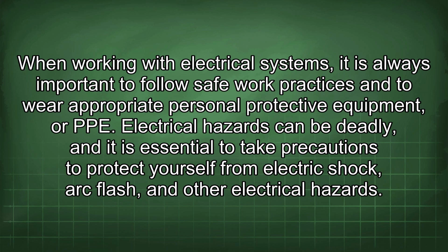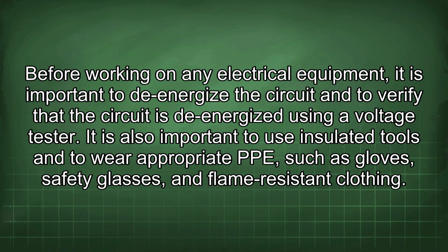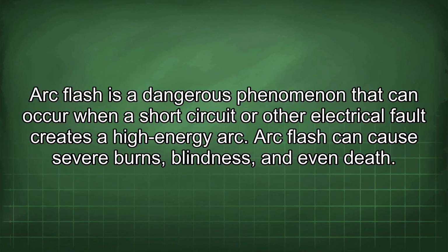Electrical hazards can be deadly, and it is essential to take precautions to protect yourself from electric shock, arc flash, and other electrical hazards. Before working on any electrical equipment, it is important to de-energize the circuit and to verify that the circuit is de-energized using a voltage tester. It is also important to use insulated tools and to wear appropriate PPE, such as gloves, safety glasses, and flame-resistant clothing. Arc flash is a dangerous phenomenon that can occur when a short circuit or other electrical fault creates a high-energy arc. Arc flash can cause severe burns, blindness, and even death.